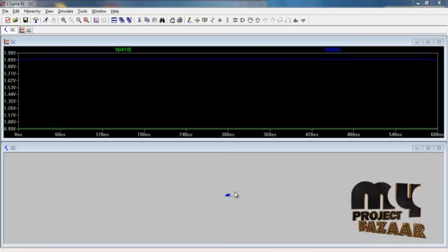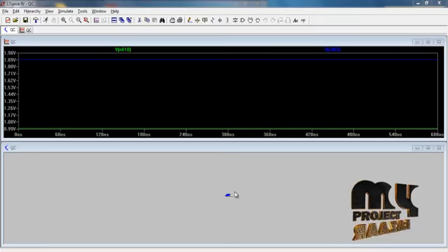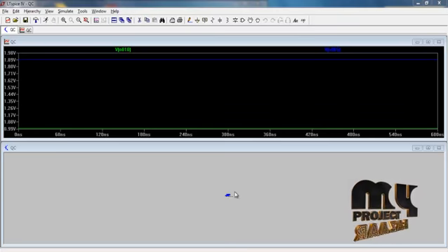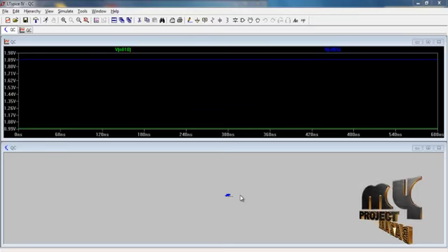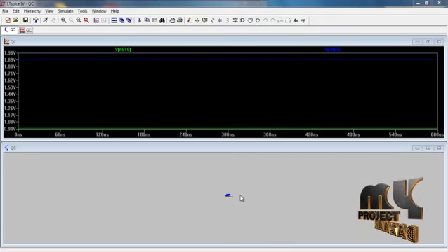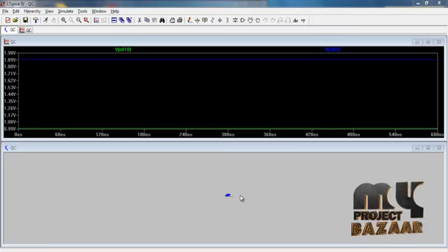Finally, we are going to see the output for our product. We have designed the circulators in the LT space. This design is the CMOS quasi-circulator using the type 2 Bridge-T network topology. The Bridge-T network uses signal cancellation technique and a band reject characteristic to reject S31.